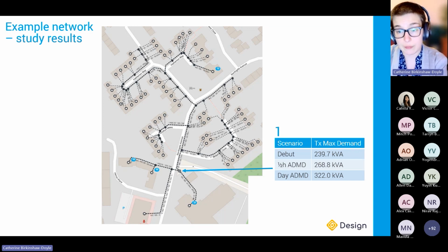And you can see this by comparing it to the half-hourly ADMD profile. The result here is about 50 kVA lower than the full ADMD approach. So you can see the immediate headroom that opens up on that transformer by properly accounting for this effect. The W approach again is slightly lower than this because it accounts for the full approach of diversity between the customer types as well.